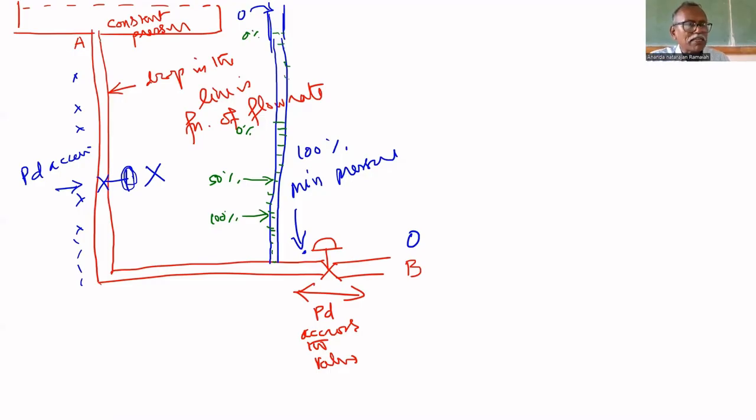So it depends upon the pressure drop in the line. This will vary, but for 100% it will be minimum. So how can I keep the pressure drop across the valve constant? For 100%, suppose the marking is here. For 50% opening, it comes here. Now I can close this hand valve to introduce additional pressure drop so that the 50% comes to this point, to C. Am I correct or not?